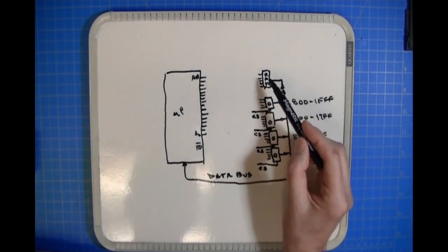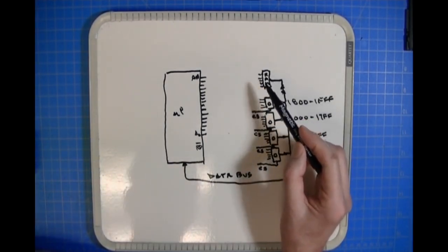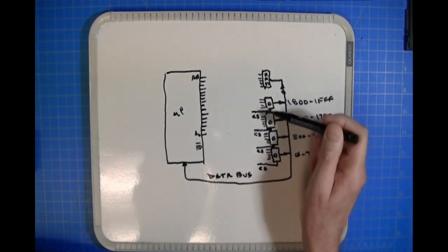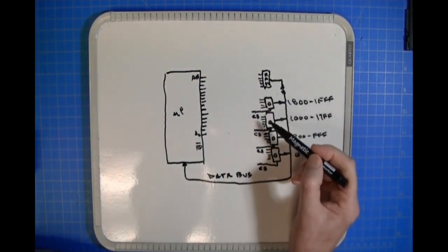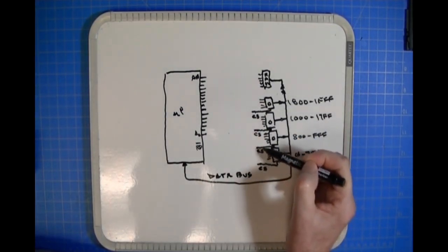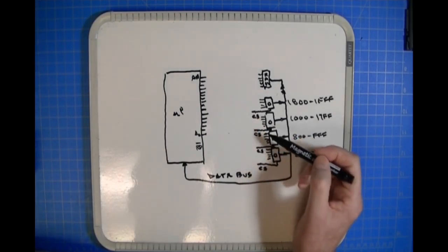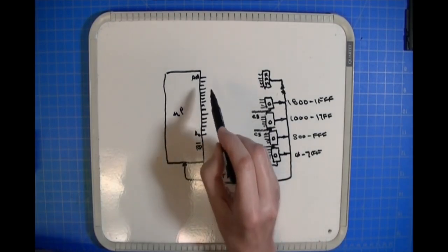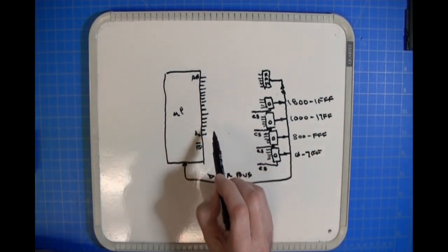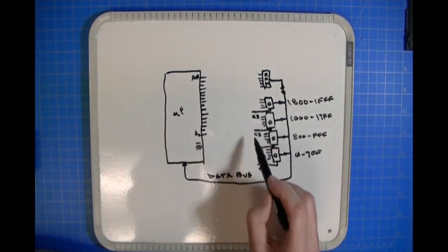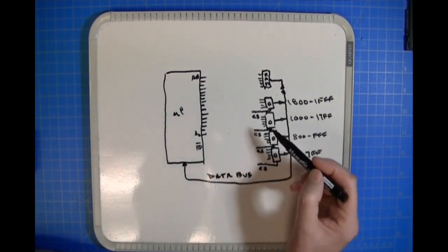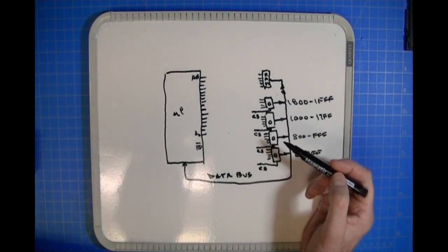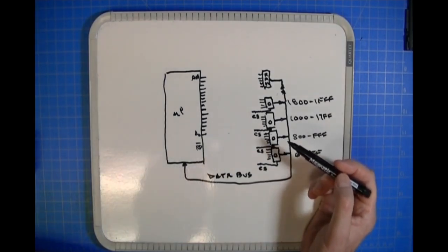The designer has to have some way to select at the appropriate address the appropriate EPROM. You can see here that he's got 4 lines which are going to select one of 4 EPROMs. So he needs digital circuitry that's going to sit in between the addresses coming out of the microprocessor and the chip select lines that are going into the EPROMs, so only the correct EPROM is going to be accessed. So that's the problem.